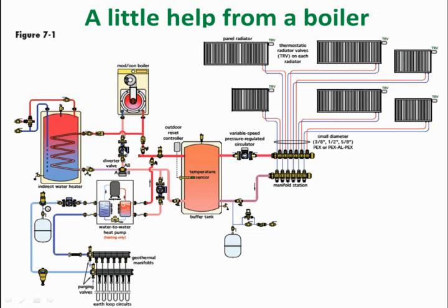You can see what happens here is the flow goes into the center port and the T in the bottom always, and it either goes to the B port or to the A port. So it's either going to go to the tank or it's going to go directly into the heating load, or the heating buffer tank, I should say. I think that's pretty much it on that drawing.